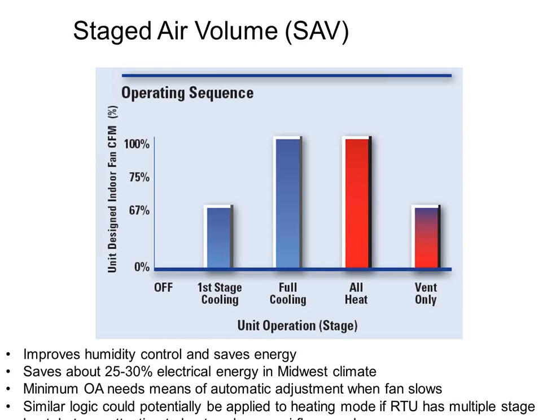If I can slow down the airflow going across the evaporator coil, it's also going to take me longer to satisfy the thermostat set point, which means I'm going to get a longer run cycle. And the slower I move the airflow through there, the more I can change the sensible heat ratio, and I can do better dehumidification that way as well. So having the staging capability combined with the fan staging capability is really a great dehumidification benefit on a rooftop unit.